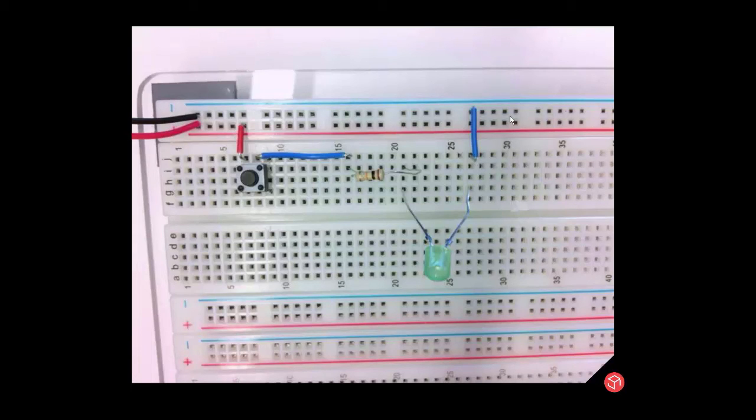So if you think about it, this is what we have. We have the current flowing as shown in this diagram from the positive to the switch. If the switch is open, of course, there's no current. The circuit is open. If you push this down, the current will continue flowing. It will go through the resistor, the LED. It's going through the LED the right way, from the positive side to the negative side, and then it will go back to ground in the power supply. So in theory, if I push this button, the LED should light up. And that's how we connect the circuit.